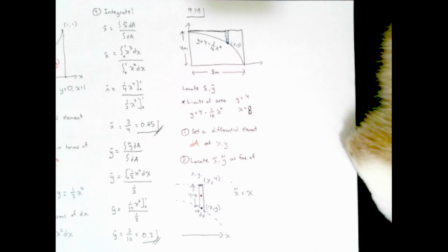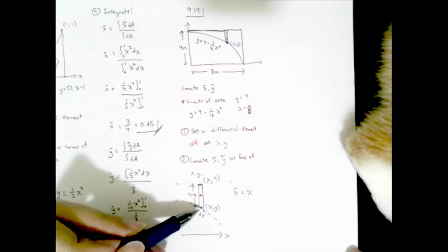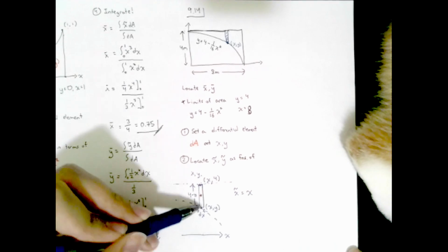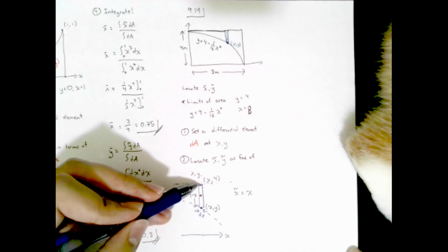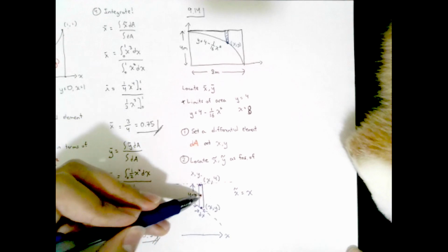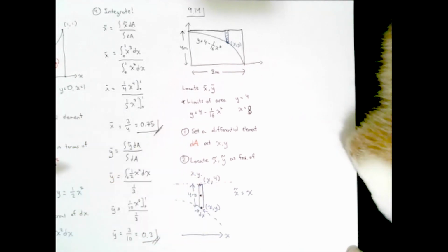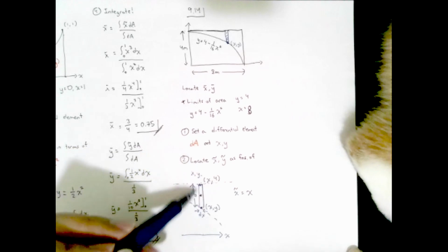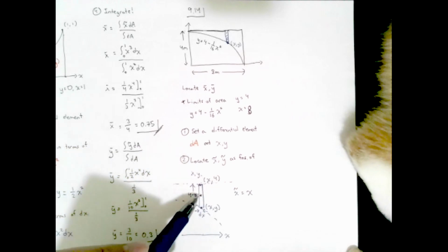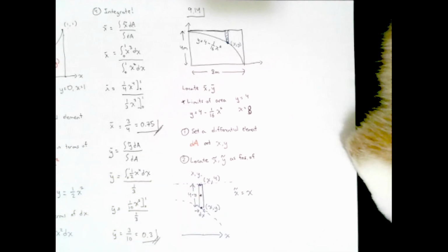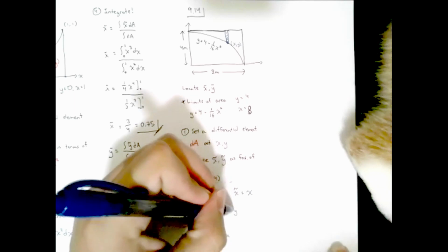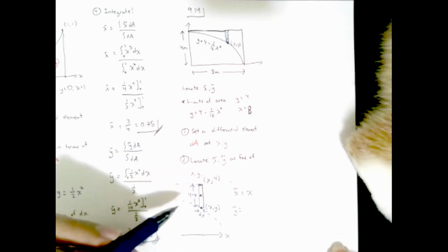Yes. Okay, but now let's look at the y coordinate. This is my point y. This is the centroid, this is y squiggly, and this is 4. Now y squiggly lies somewhere in between y and 4, right? Based on the size of this rectangle, where do you think y squiggly lies relative to the rectangle only? Is it 4 minus y over 2? Exactly, right? So relative to the rectangle, my y squiggly is going to be at 4 minus y over 2.